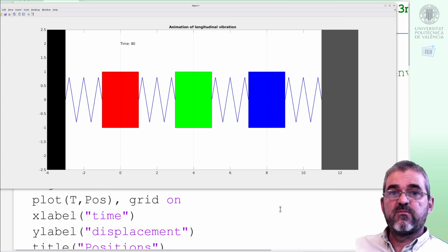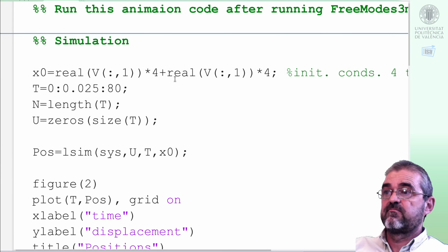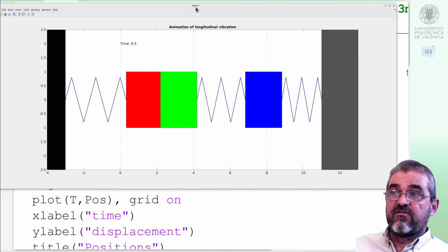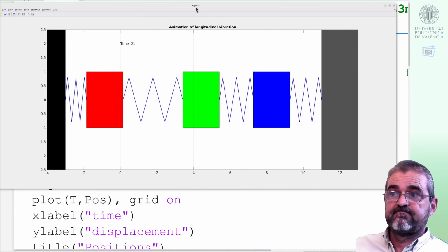The real part can be used to compute settling time, the imaginary part gives the oscillation frequency, and the eigenvector tells us the shape of this vibration mode. Of course, if initial conditions are not exactly one of the eigenvectors, then the overall response will be, by superposition, a mixture of the responses associated to each of the modes.